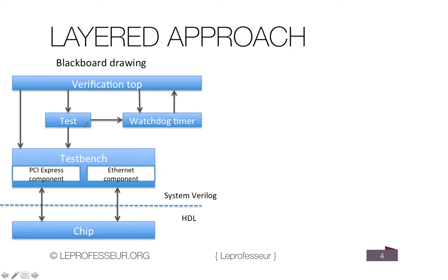It becomes important when we are using a randomized approach for giving stimulus. Maybe that particular randomized input makes the system hang, and we don't want our system to hang forever. So there is a watchdog timer in this module, as well as the scoreboarding features, that will keep track of the time, and when the time elapses, it will kill the particular stimulus which is causing the problem. So we can revisit what stimulus caused the problem, and we can fix the bug in the system.